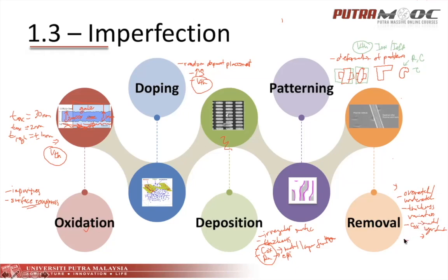Alright, so what else could vary? The resistance as well. This is in the metal layer. You can observe some under etch or maybe what we call dishing effects. So we can observe dishing effect, and then we can also observe erosion effect. So it can vary the resistance on the metal layer if you have these kinds of effects.